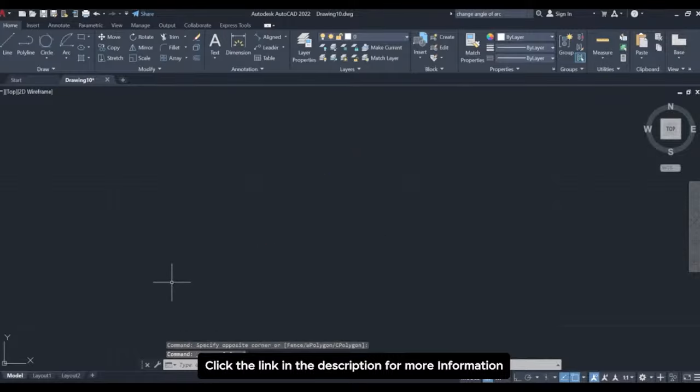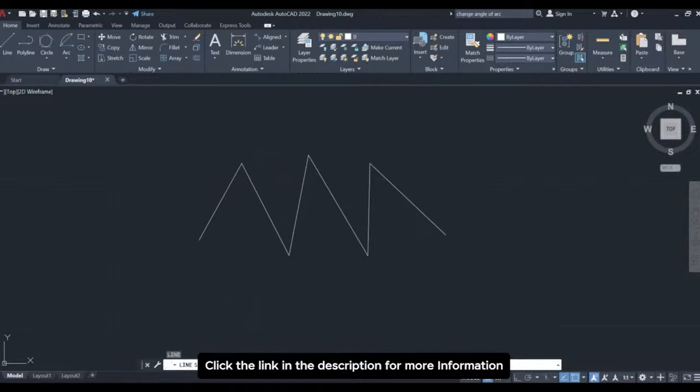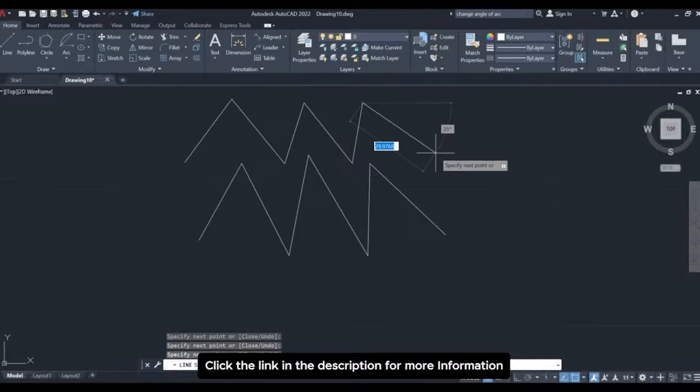The last command is a polyline. The polyline command, which is present over here, is given by PL, enter. Now, in the polyline, you can actually make zigzag lines like this and stop. The difference between a polyline and a normal line. Let's make a normal line as well. And you'd probably be telling me, yeah, what's the point of actually making a polyline when there's a normal line command?